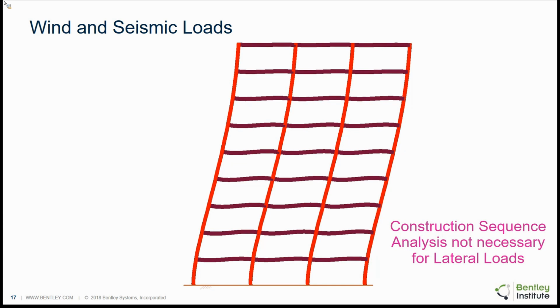Now, for a very tall structure, there often is a concern that some high winds or an earthquake of some magnitude could strike, and you certainly could build intermediate models, analyzing and then designing accordingly. But in general, an elaborate construction sequence analysis, I wouldn't consider to be necessary.